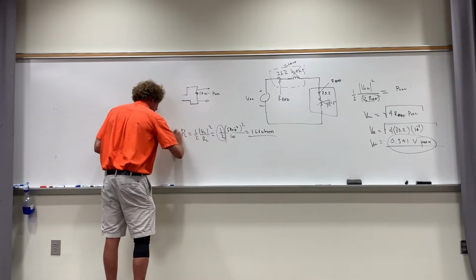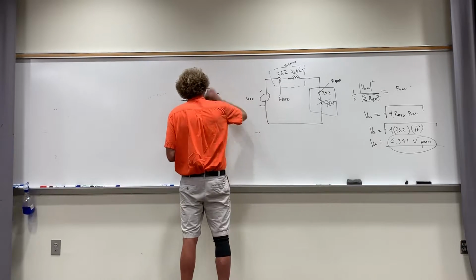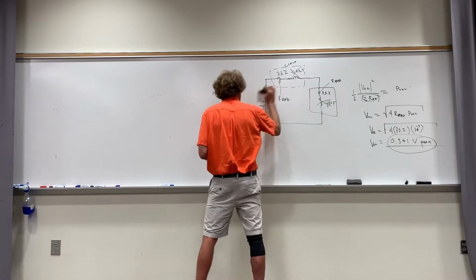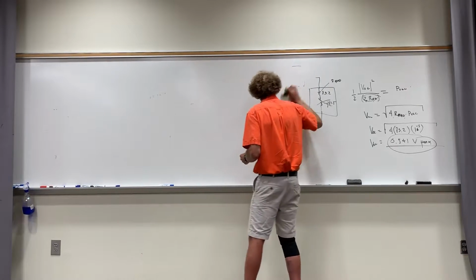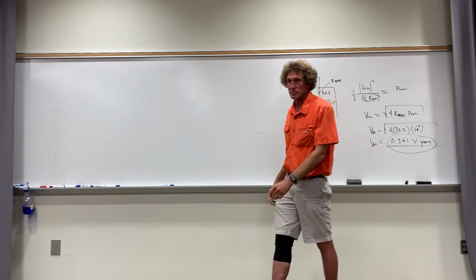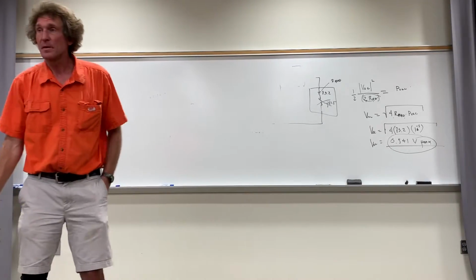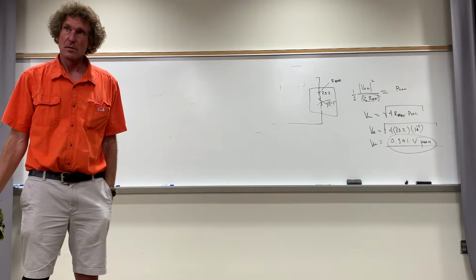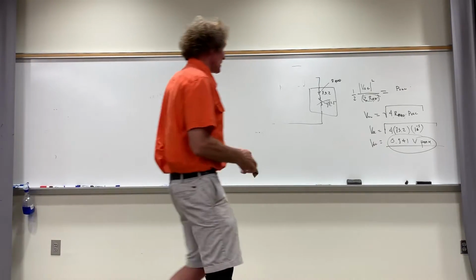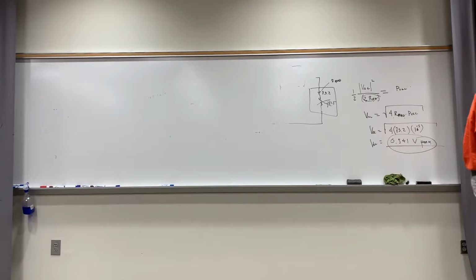All right, that'd be a good problem. How about the next problem? Because I think I gave you a series of problems that were all like this. Ask a question real quick. It says that 1/2 P received is equal to V_L squared over 2Z_L. Which means that P received is V_L squared over Z_L, if it's matched.